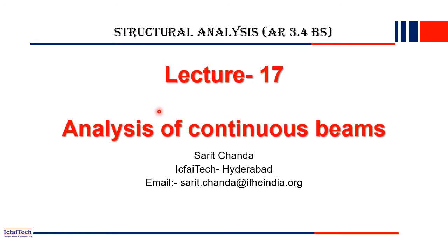And if you recall, all the structures we have discussed till now are determinate structures. That is, we can analyze the structure using the equations of equilibrium. Already we know that in a 2D structure there are three equilibrium equations: the summation of all horizontal forces equal to 0, the summation of all vertical forces equal to 0, and the summation of all moments about any point equal to 0.